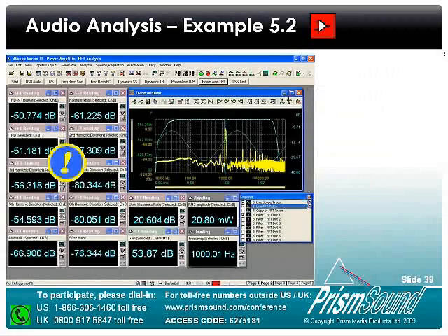One of the things that we're going to look at, we're going to have a look at a couple of different test setups here. Initially, we're going to look at quantifying the output power from the amplifiers, which is one of the first things you're likely to want to do, having designed, built, or attempted to verify the performance of a power amplifier. We're then going to move on to some very interesting spectral analysis tools, some really unique and powerful tools that we have in the D-scope system in particular, that exploit the power of the host PC to do a lot of numerical calculations and post-processing on FFT data, so spectral processing. And we have a series of instruments called our smart FFTs, or FFT detectors, that we're going to look at in more detail and see how they can really help us to understand how our device under test, whether it's a power amplifier or any other kind of audio device, is really truly performing.